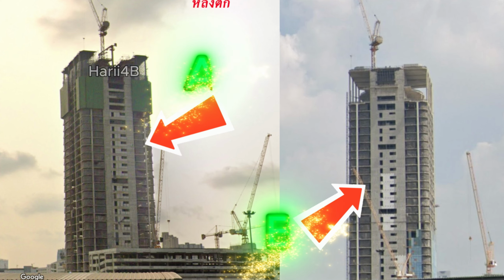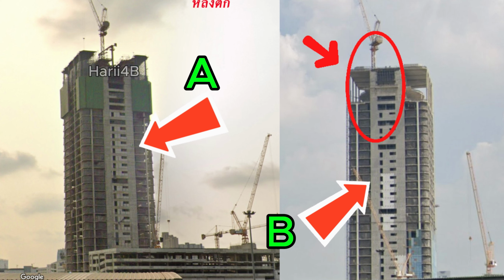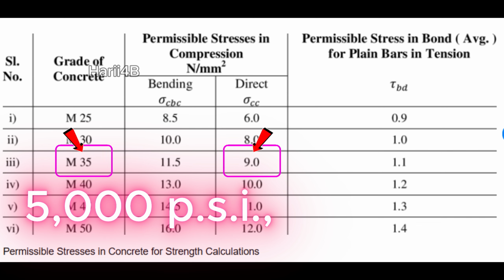Going back to core walls. Shown is core wall A, as well as core wall B. The climbing tower crane is positioned on top of core wall B. Let's evaluate the strength or the load carrying capacity of both core walls. Let's assume the concrete grade or strength is 5,000 psi, or the M35 type concrete. The allowable direct compression strength shall be 9.0 megapascals.